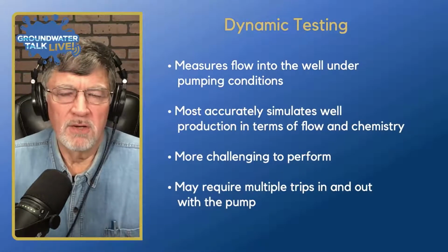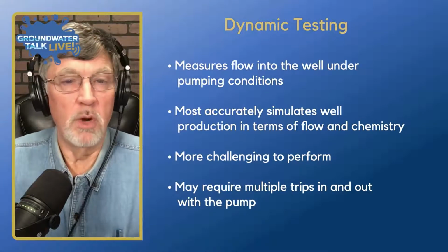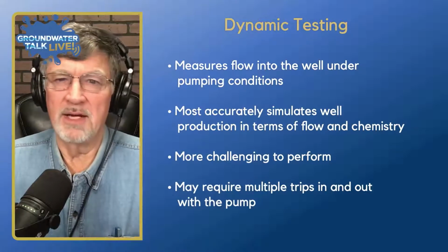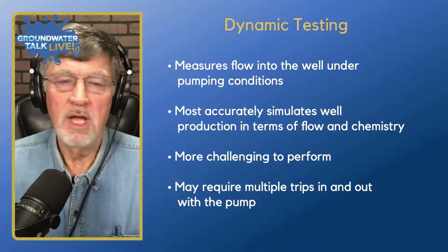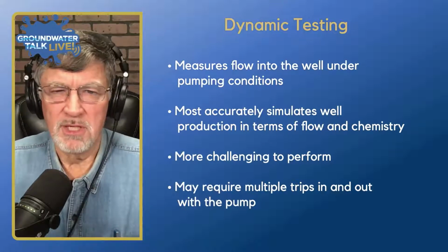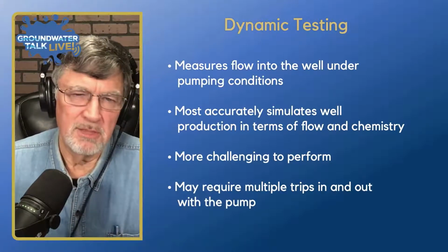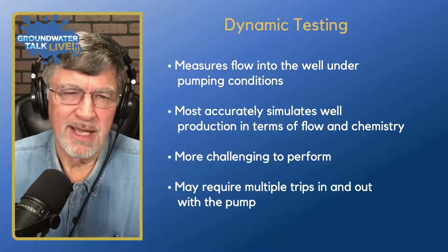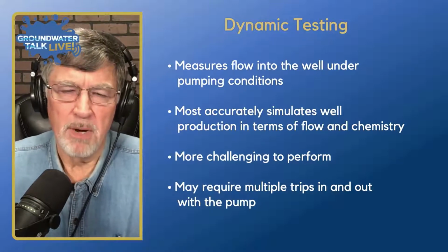Probably more of concern to us for our well design is dynamic testing, and that's going to measure the flow into the well under pumping conditions, which means we're going to do this testing while there is a pump in the well and it's actively pumping. So it most accurately simulates well production in terms of flow and chemistry from the individual zones. A little more challenging to perform because you need to take the pump out, you need to put in the tool you're going to use to measure things, you need to put the pump back in, and then do your testing. You can't pull your tooling above the pump, so you have to place your pump appropriately.